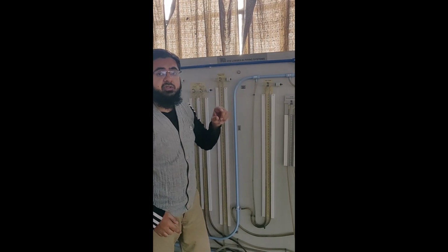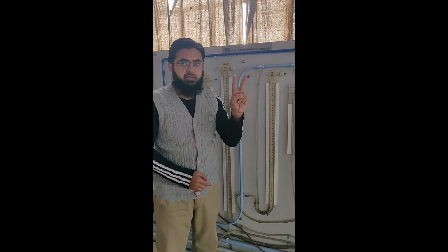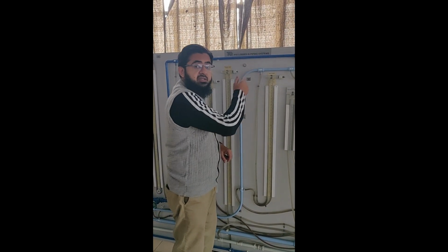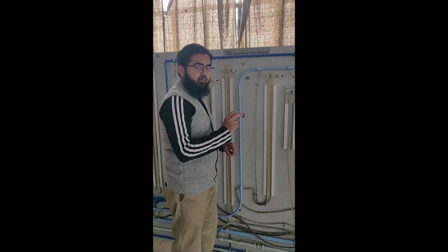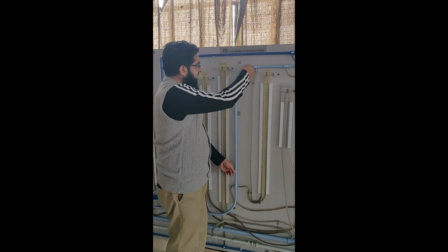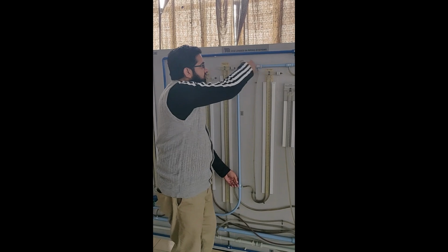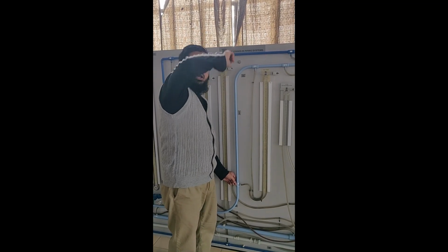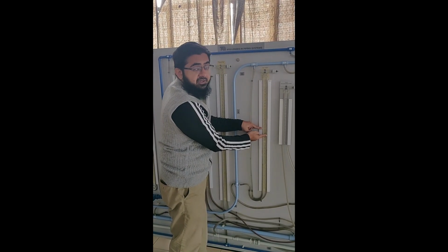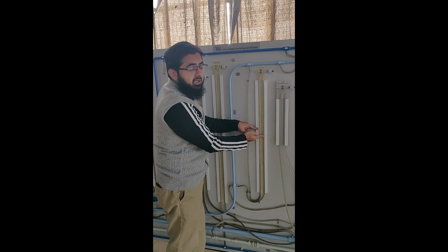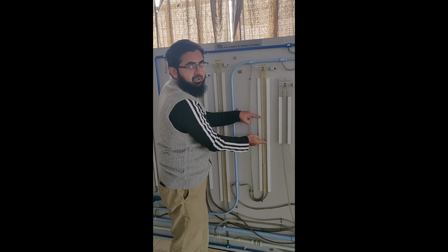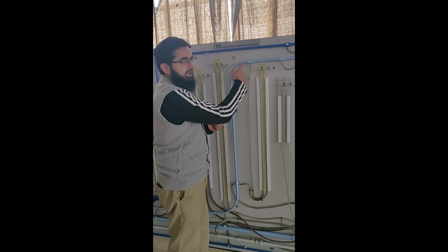Whatever difference we would see here would be because of the pressure drop from here till here. This pressure drop would be because of two reasons. One would be the frictional loss for this complete length, that is the major loss, and the second would be due to this bend. So let's say if instead of this bend, this was a straight pipe till here, and because of that straight pipe we would have some kind of difference in level here, some kind of pressure drop. Now when we made this bend, this pressure drop would become even more, because we are adding an additional loss due to bend.